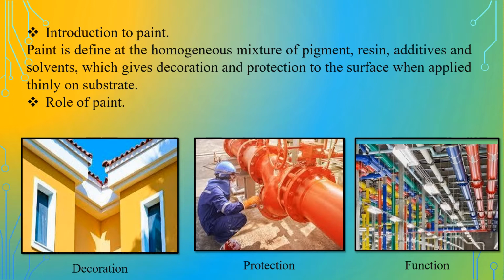So the first purpose in protection is to avoid the contact of that bare metal with the atmospheric climatic conditions. For the protection, we have different mechanisms. Coating is a physical mechanism to protect the base metal. Then there is a chemical protection mechanism also, where we use different types of metals like zinc and other metals.